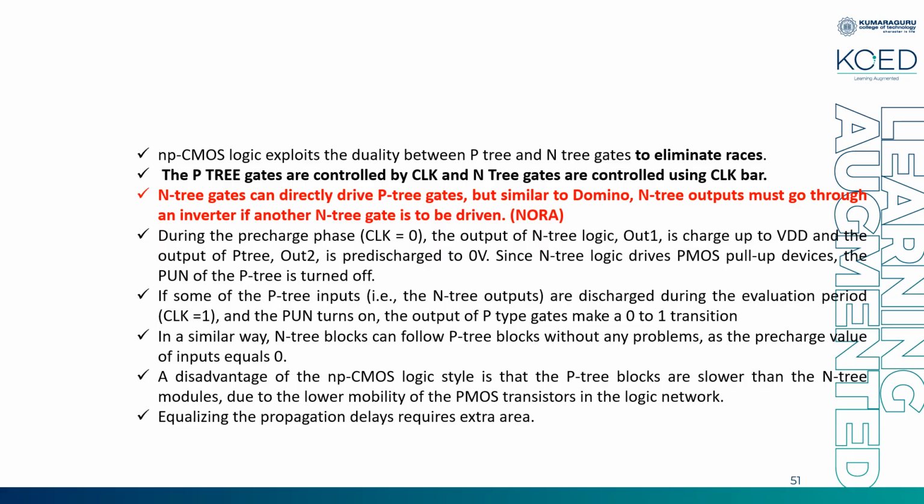So what is the disadvantage here? Both transitions are easily possible. But compared to when you design the logic using PMOS, generally PMOS is less efficient when compared to NMOS. If you see why, PMOS does not give the output drain current the way NMOS does. The reason is generally that mobility of P type is low. So you have less mobility in case of P type materials, and the reason you follow the sizing ratio is to compare the efficiency between NMOS and PMOS.